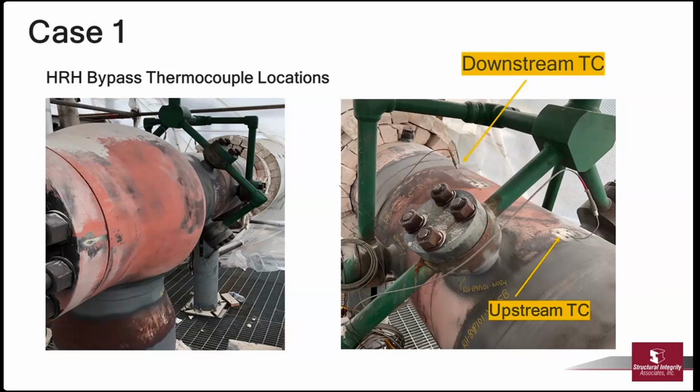And obviously those are not post-weld heat treated, and the depth of that weld is much, much deeper than you'd see on the spot welds here. But looking at this hot reheat bypass, you can see this is fairly typical of a lot of these, where you've got a very, very large change in diameter, wall thickness, and probably material, combined with a 90-degree valve. So you've got stress concentrations due to all those things, and then usually a lot of flow issues. So it's not surprising that you're going to have issues on these.